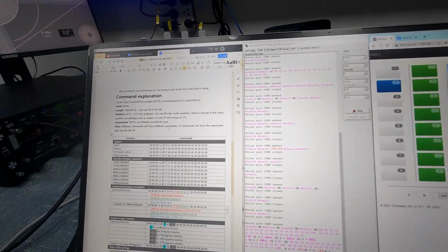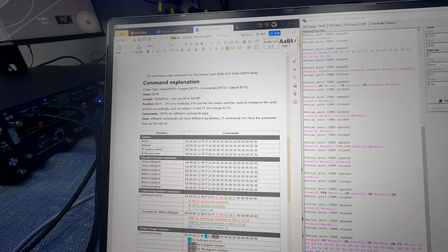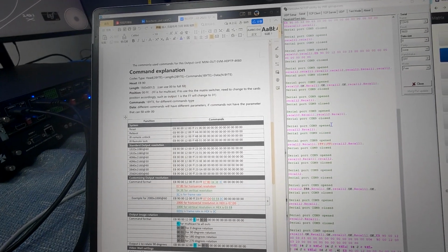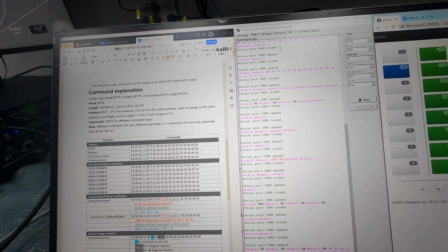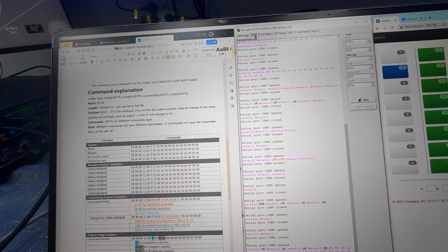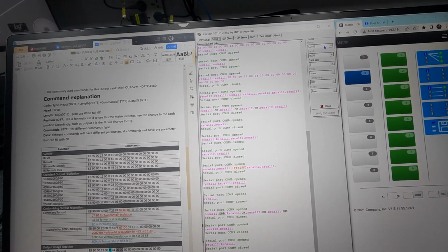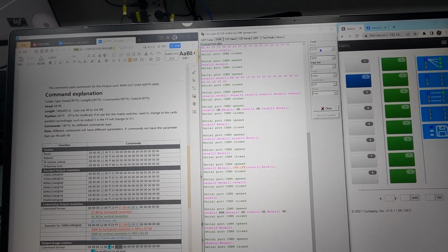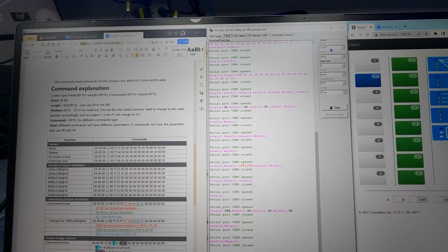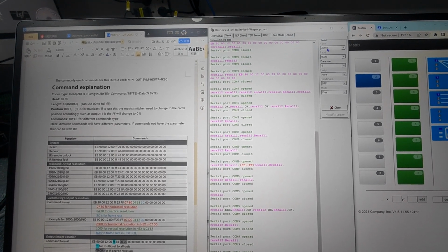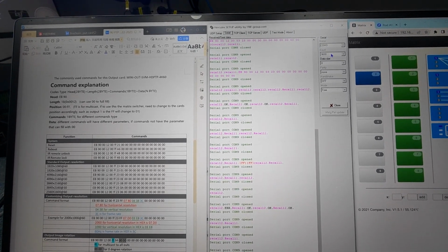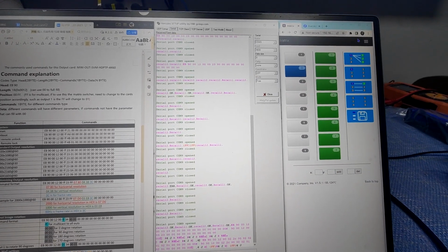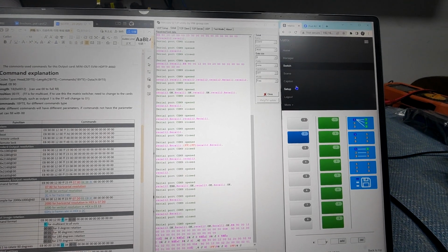Okay, so now these are the RS232 commands which we can use to set up the output resolutions. And this is the RS232 software which I'm using, a serial tool. My COM port is COM9, but we can get the COM port from the computer's device manager. Different computers will have different COM ports, and the baud rate we can get from our matrix switcher web GUI control, from the settings tab.